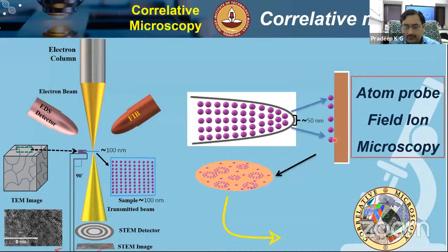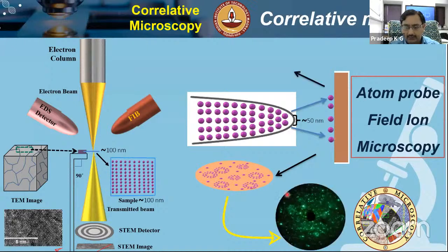So this is what we are going to see. The darker area is a detector when there is no atom hitting, whereas these bright spots, as you see, are all images of individual atoms sitting on the surface of a sharp needle like this. That means wherever there is an atom, the imaging species gets polarized to that particular location, and the ionized gas species will hit the detector starting from that location, which is being nicely mapped here.